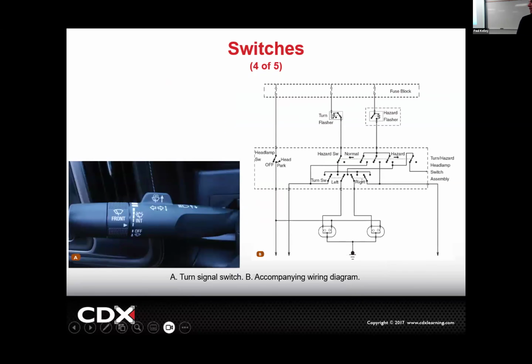So if you look at a wiring diagram, there's your multifunction switch. So if, let's say, you were trying to diagnose that switch, you have to say, well, which one am I really worried about? If the customer's concern is my headlights don't work, I don't really want you or any technician to go in and test all these switches, right? There's a lot of micro switches within the one big switch assembly. If it's a headlight issue, I'd focus more over here.